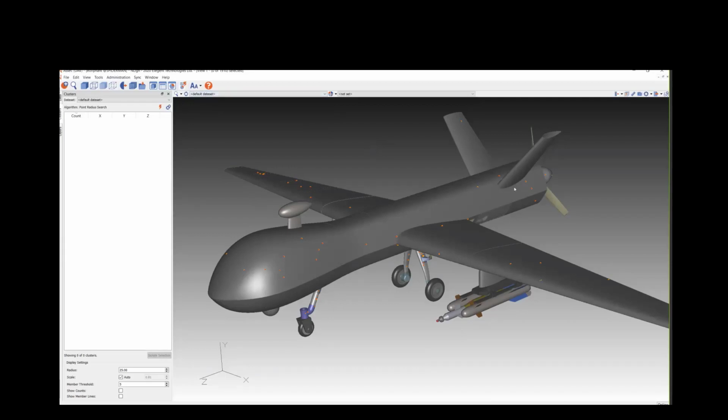On this view window, I wanted to go through several of the tools up here. One of the major ones is the different data sets. This is basically what filters I want to apply. So I could apply one that says, just show me the corrosion records. And there are 34 different corrosion records on this aircraft. Looks like the majority of them are here on the landing gear. Or I could apply the default data set, or the default filter, which basically brings in every record that has ever been recorded on this aircraft.